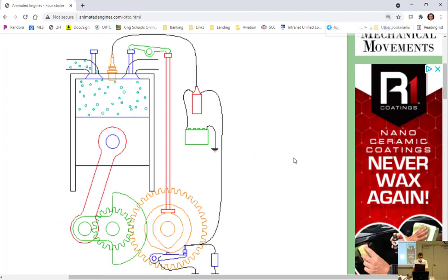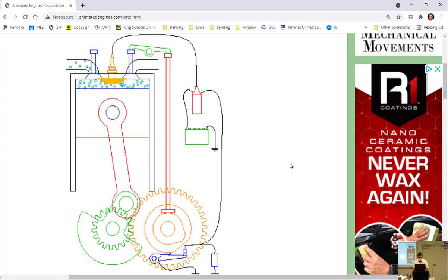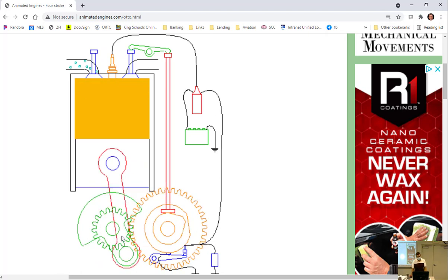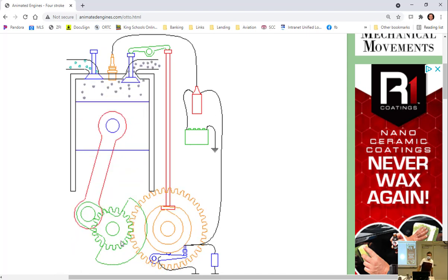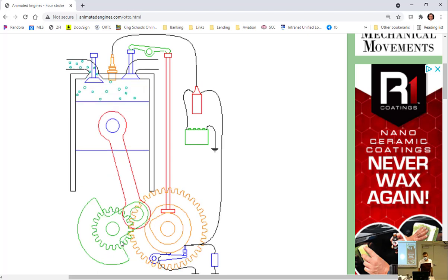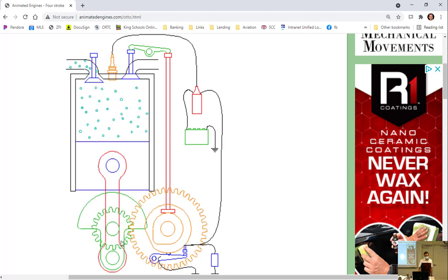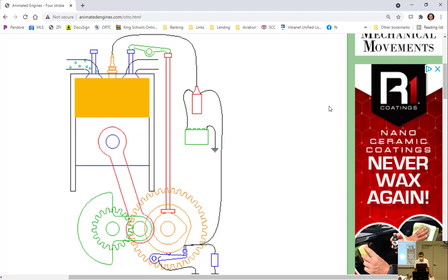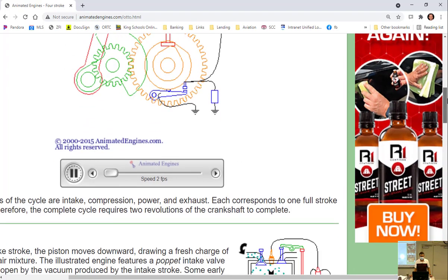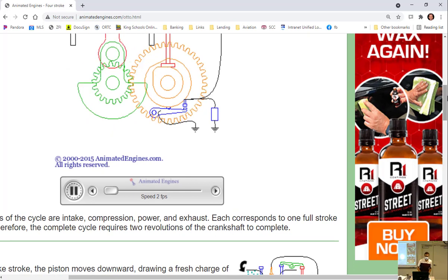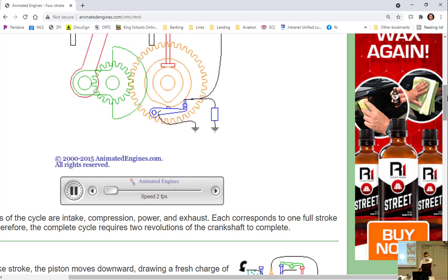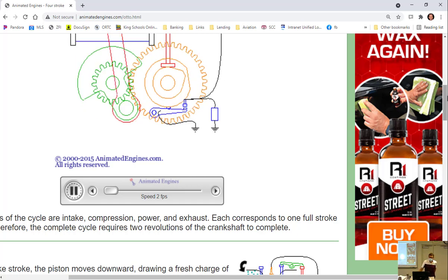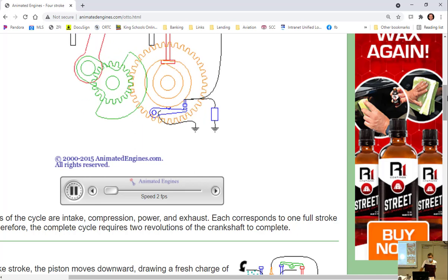And the reason why I say that the camshaft is the brains of the operation is because here's the green crankshaft going around and around. Exhaust, intake, compression. Does the camshaft know the difference? No. If I were to roll this and say, you can't see what's going on, just look at the crankshaft, do you know what stroke it's on? It's up, it's down.